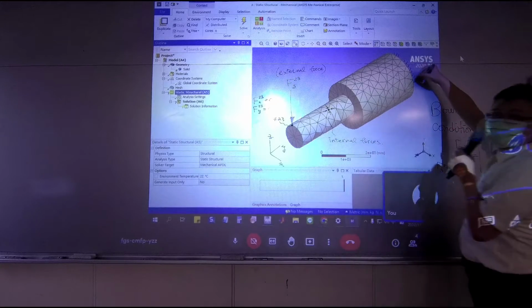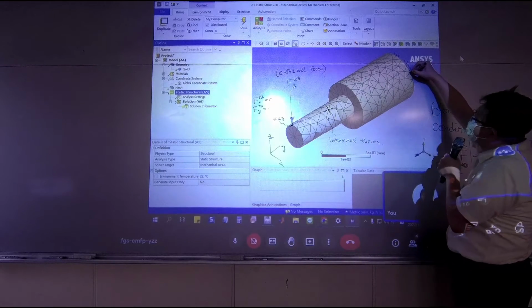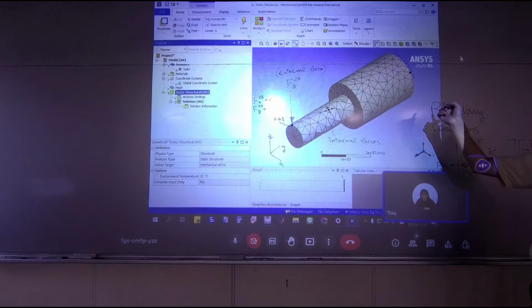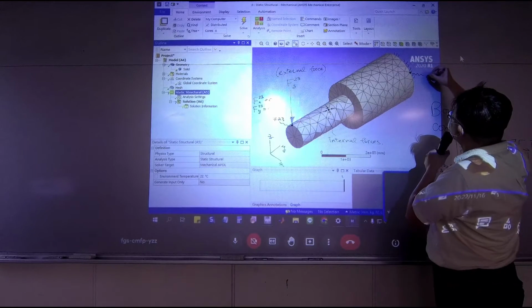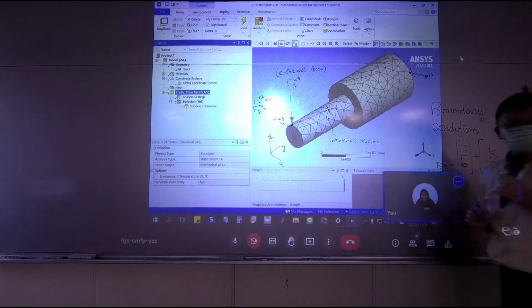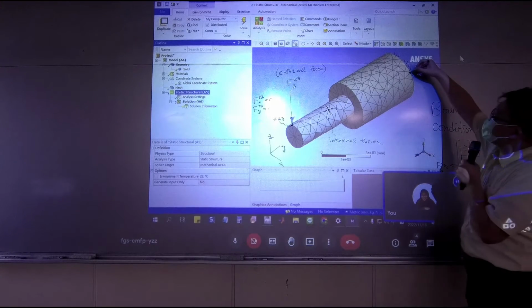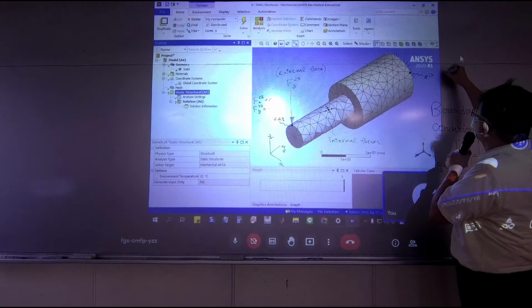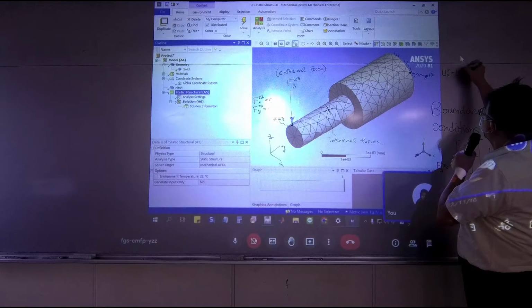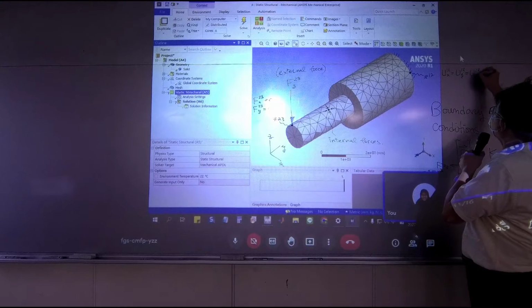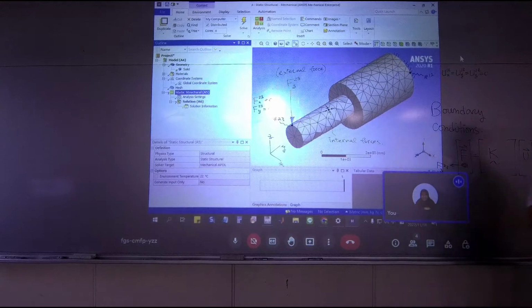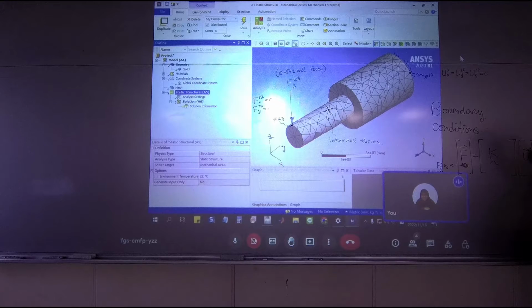And when we assign boundary condition right here, like this one, we claim it's fixed on the wall. So for example, this is node number 12. In that case, because this is fixed, we are sure U12X, U12Y, U12Z, they are 0, because you say it's fixed. So in this case, there are 3 numbers here. They are U12X, U12Y, U12Z. They are all 0.